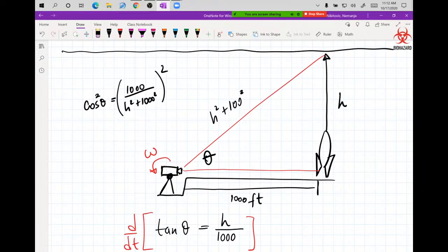So when you put all of those things together, the simple input of the height, which is a constant input, the software constantly computes what angle it should be, which is fed into the power supply, which supplies a certain amount of voltage to the servo motor, and the servo motor turns exactly for that angle that is calculated through the formula.